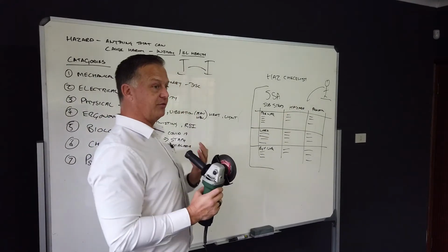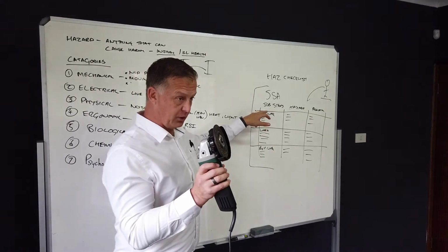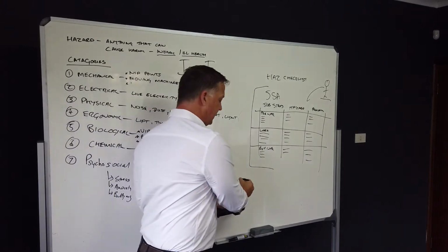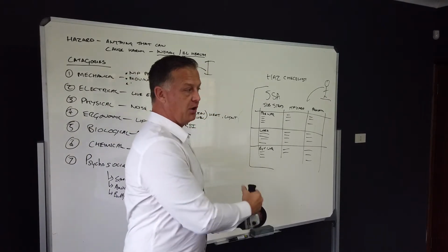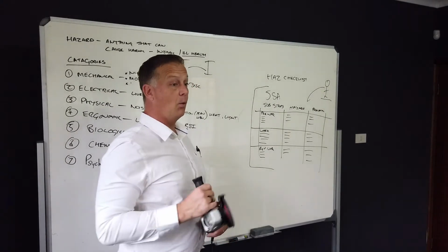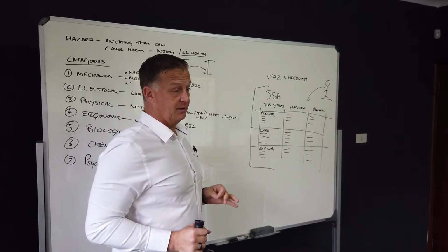What about the work environment as well? So I need to inspect the hazards with the equipment, also with the work area. If I'm going to be grinding and sparks are going to be created by this, what else do I want to be aware of in this area? Housekeeping. Why housekeeping? Good statement. To avoid hazard or any injury.